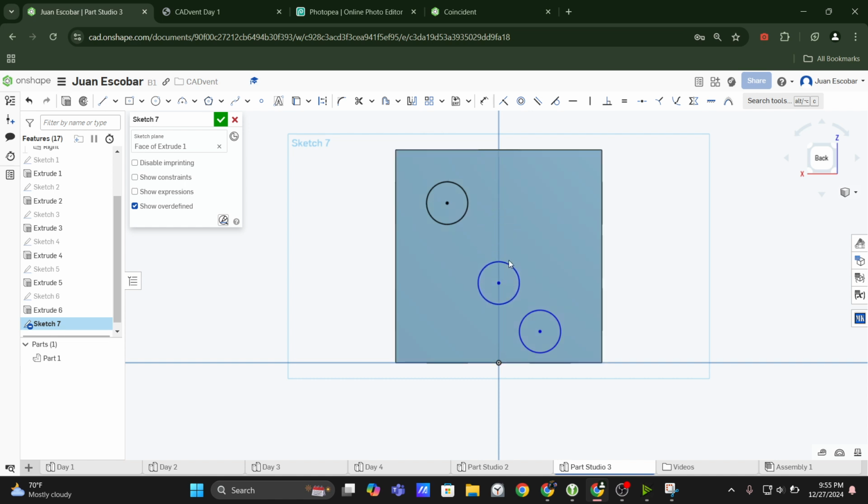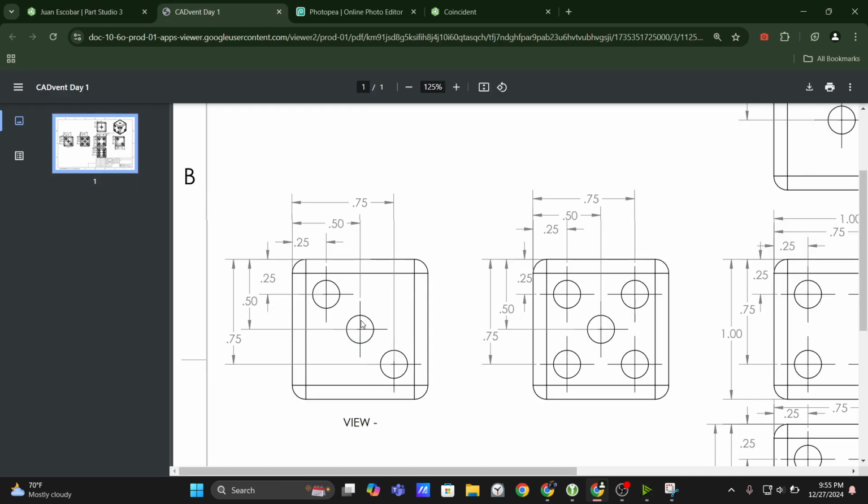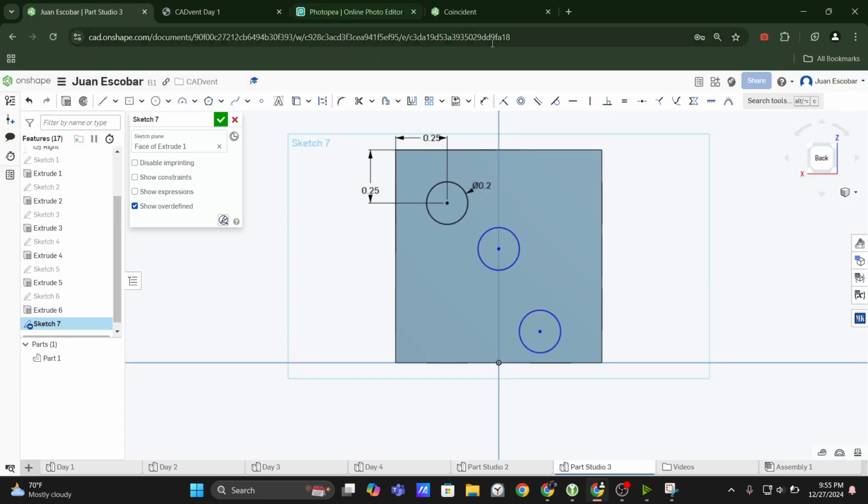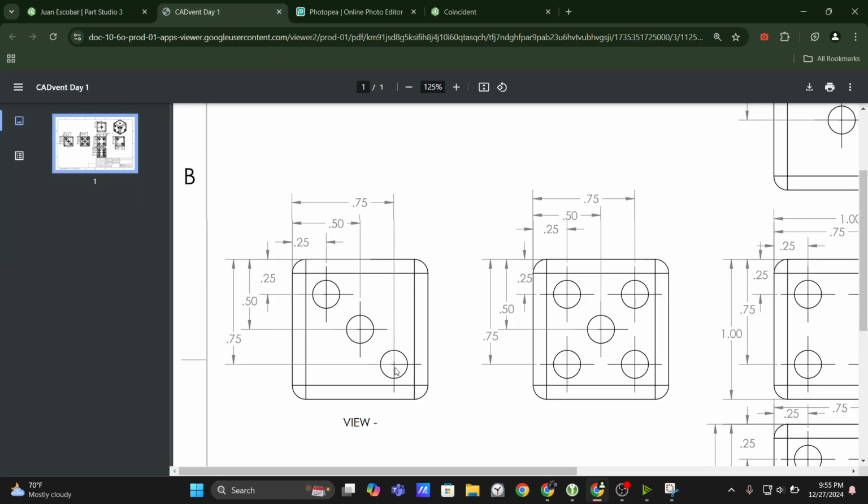And you can see, okay, it's constrained horizontally, but now we'll constrain it vertically. From here to the top face, looking to the side, here to the top, is 0.5. So I'm going to click here, add 0.5. Cool. Last one. Here to the side is going to be looking vertically, 0.75.